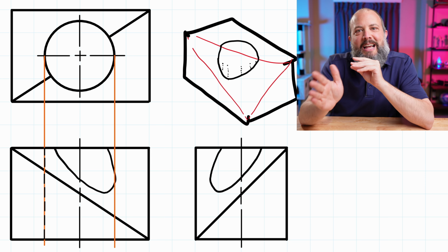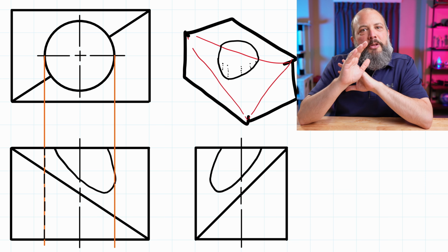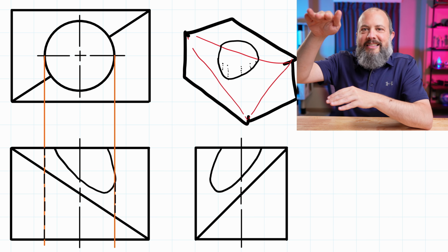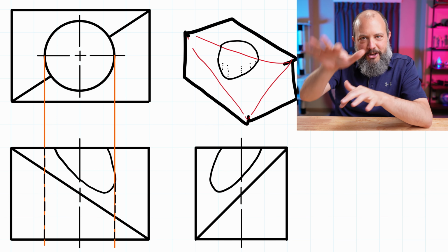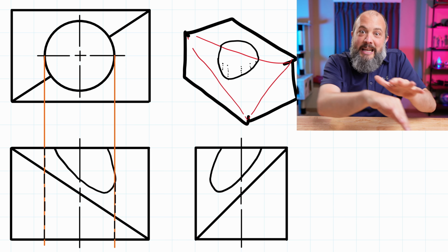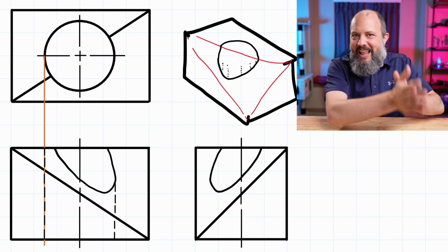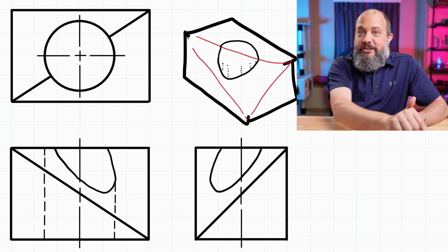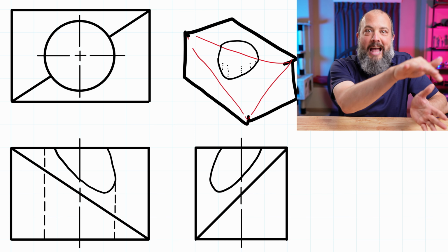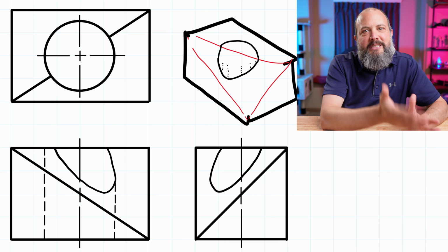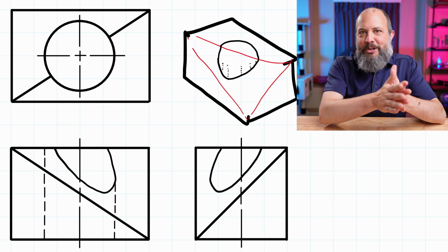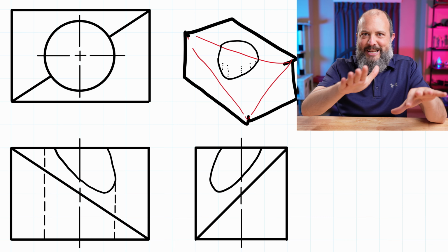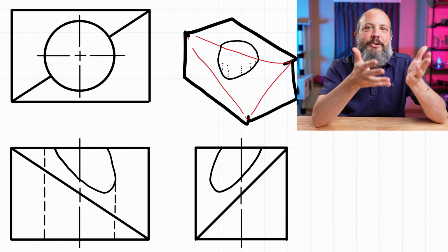But the right side of the hole, and this is probably the most common mistake a student would make on this one, the hole is not all the way at the top of the shape, right? Because of the oblique cutout, it's dipped a little bit lower. So the hidden line, the hole at the edge, would actually start at that quadrant. Like it starts partially down the drawing, not all the way up at the top. And again, because at that point of the drawing, the top is just the flat top triangular surface. The hole is in the middle of that angled face.